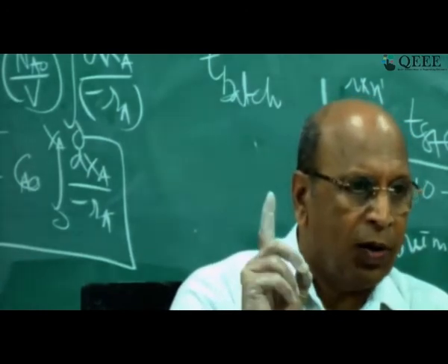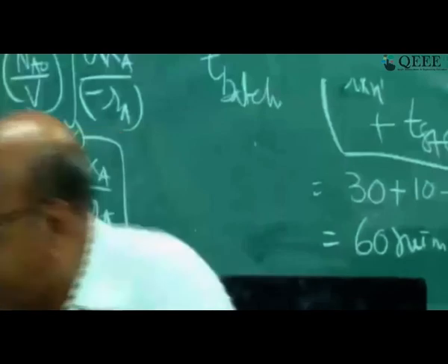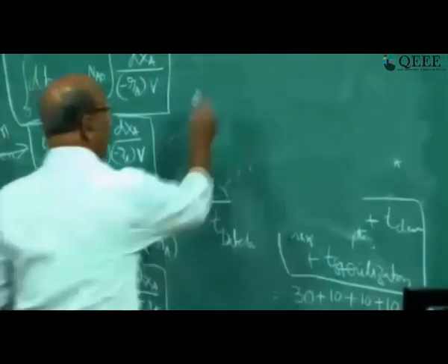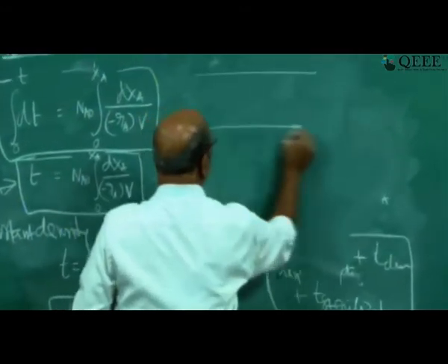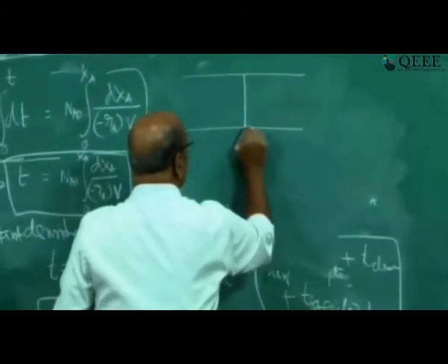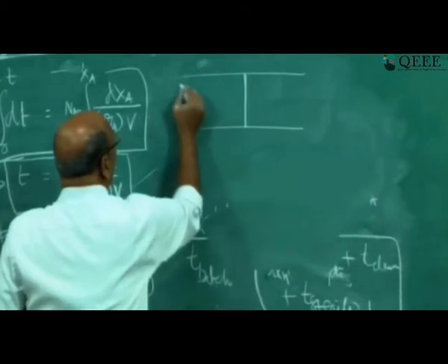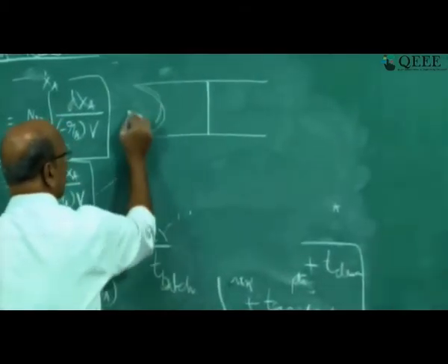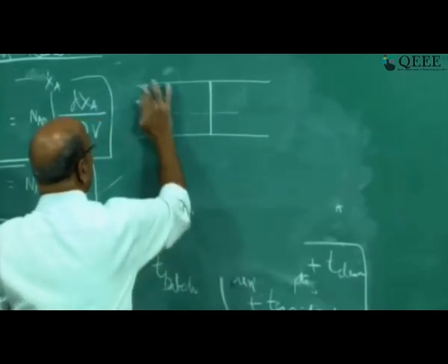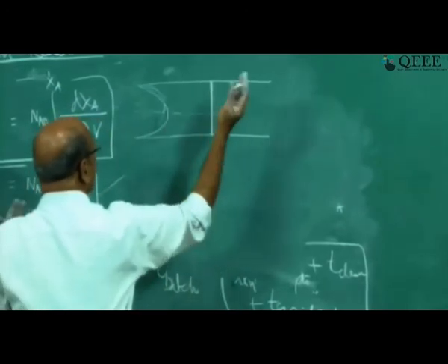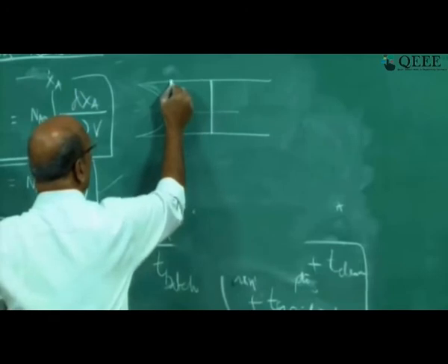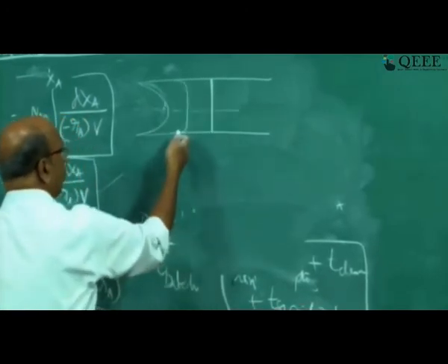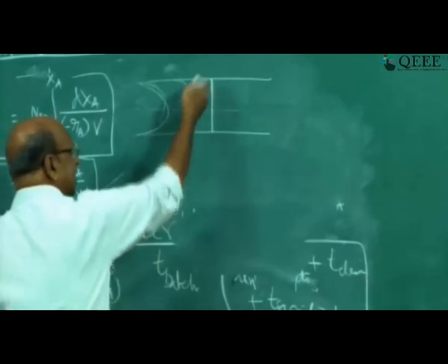So when do you actually get real plug flow, that is, this kind of velocity profile? I have shown you that for laminar flow you get a parabolic velocity profile, right? And when you have Reynolds numbers of something like 20,000 or so, you may have this kind of profile, but still it is not a flat profile.